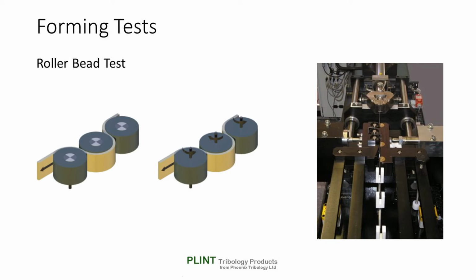It should be noted that applying too high a clamping force will simply load the tool against the stops and render measurement of the normal force on the specimen meaningless.